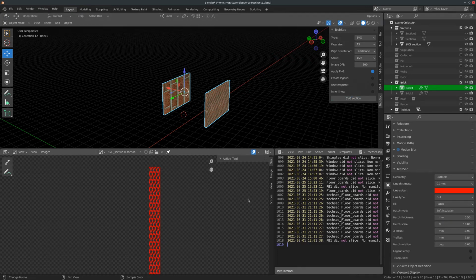And again, as you can see, arranging your patterns so that they look the way you want them to look and align with your object the way you want them to align is cumbersome in SVG mode. I'm only doing it now to show you the options. Really, if you want to adjust patterns to fit geometry, then either scaled or free modes would be the modes that you would use.